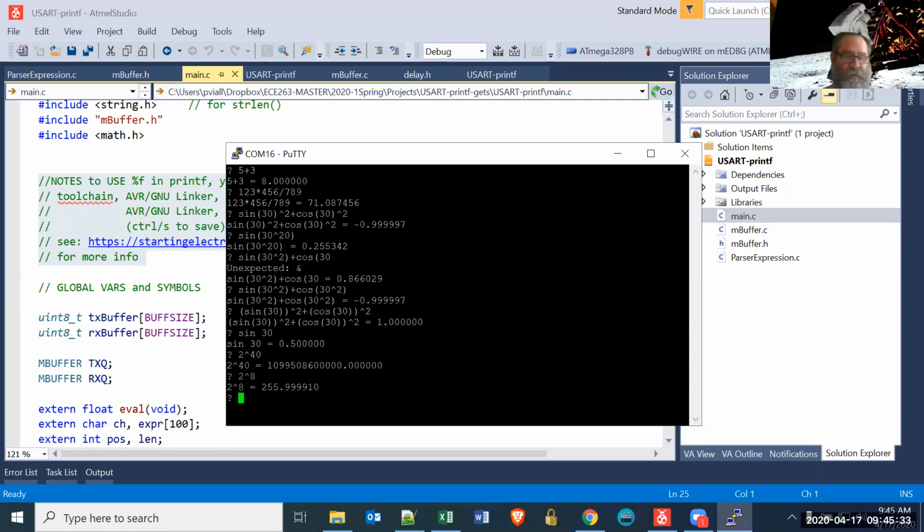Okay, yep. All right, today then, we are going to look at a new concept known as analog input. Most of everything you've done in digital logic and in this course is ones and zeros. It's either 5 volts and 0 volts, or if you're working with some technologies, it's 3.3 volts for a 1 and 0 for a 0. If you're working with RS-232, it's minus 12 for a 1 and plus 12 for a 0, but it's discrete voltages.